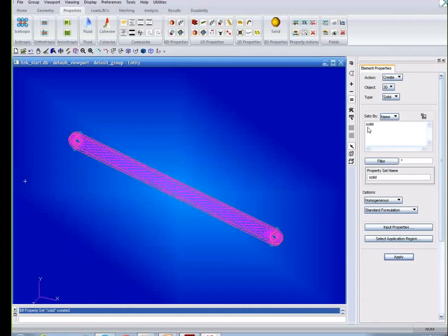So now I've got the steel meshed beam, and before I can run the analysis, I have to specify what are called the attachment degrees of freedom. Remember, in the Adams model, this link was attached at each end through a marker. We need to have nodes where those markers are in the Adams model, and that's why I created those nodes at the center.